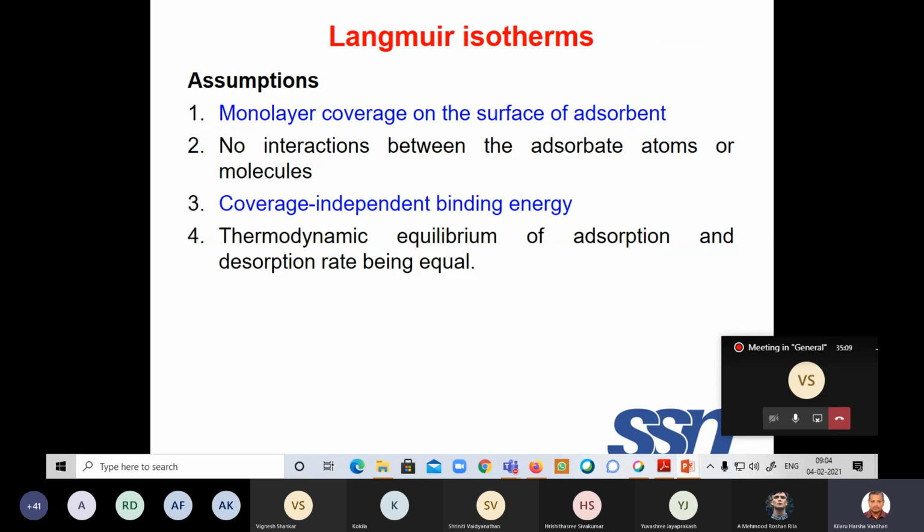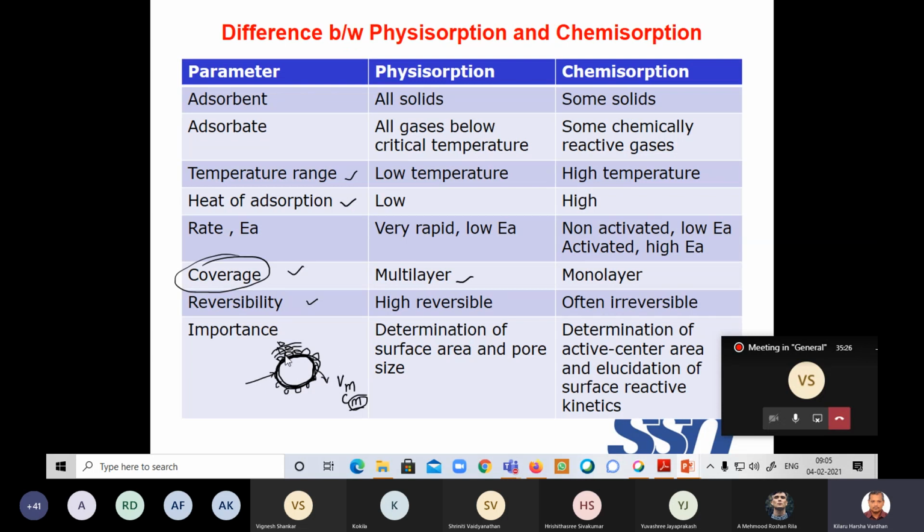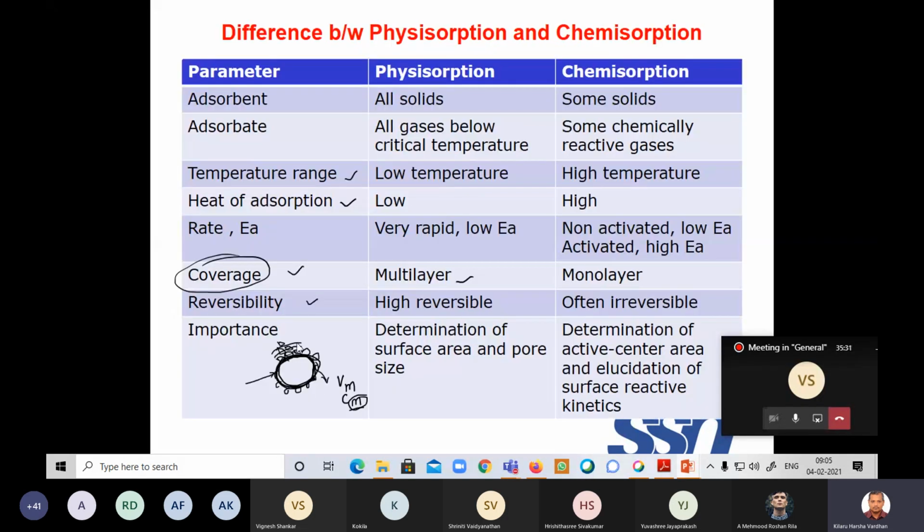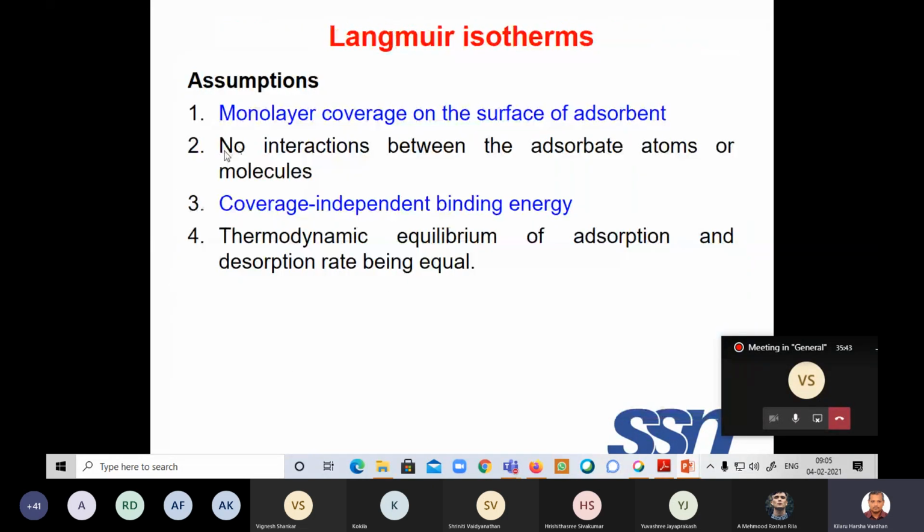Based on this, adsorption will generally be given in terms of isotherms. So the Langmuir isotherm is very popular. You might have already discussed that. In the Langmuir isotherm, you make some assumptions: monolayer coverage of the solid particles. I told you what monolayer coverage is. You will assume this, but generally it will be multilayer. Even though there is multilayer, it becomes difficult for you to assume. If you assume multilayer, equations become complex. Therefore, you assume it is a monolayer.